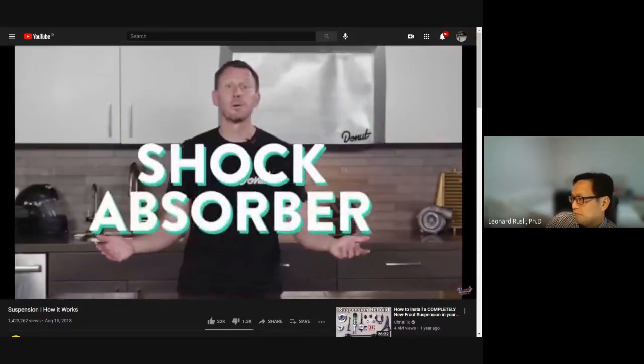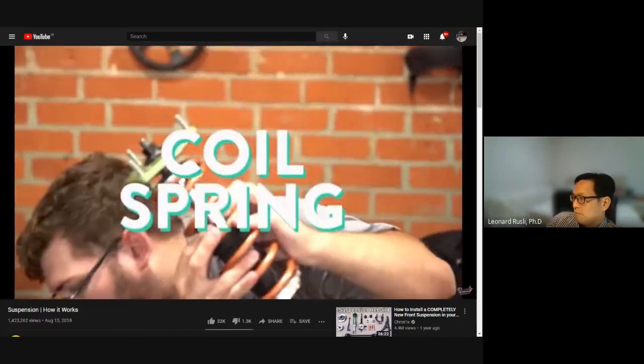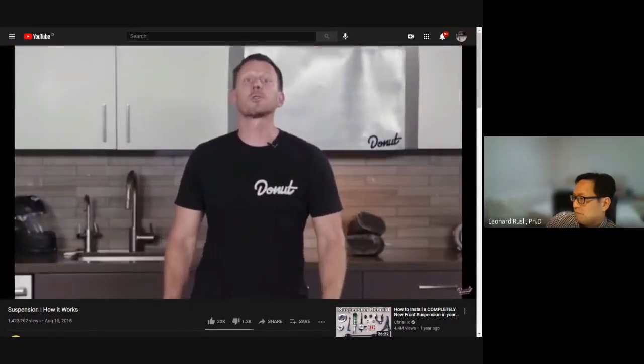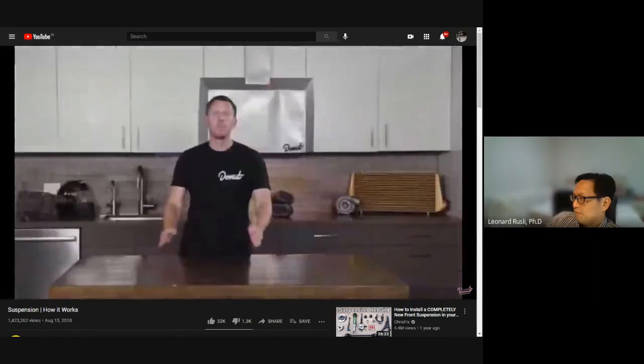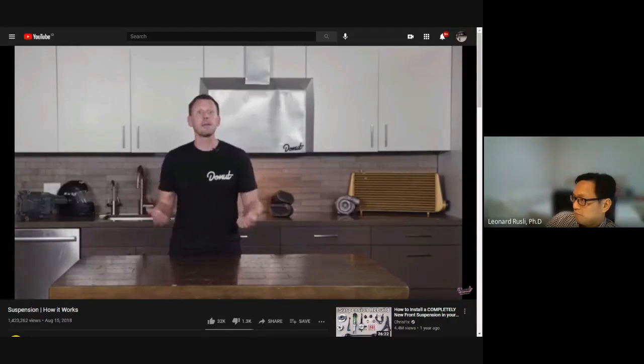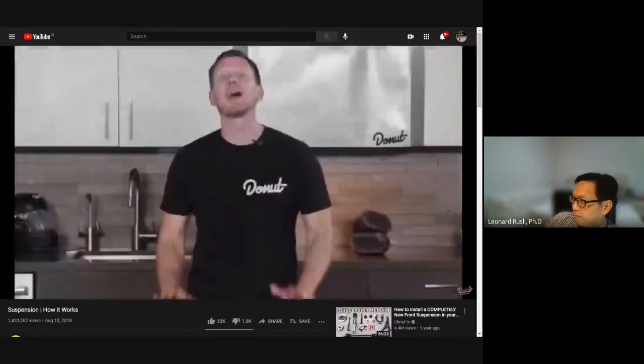Basically, it's a shock absorber mounted inside a coil spring. Struts provide two jobs: dampening function like the shock absorbers, and structural support for the vehicle's suspension. They do a bit more than shock absorbers, which don't support vehicle weight. They only control the speed at which the weight is transferred in a car, not the weight itself.